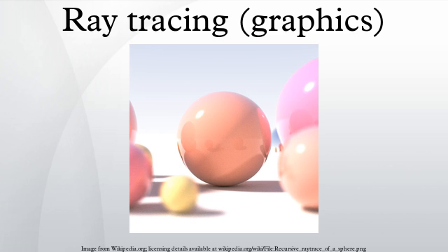Note that using a hierarchical system like this changes the intersection computational time from a linear dependence on the number of objects to something between linear and a logarithmic dependence.